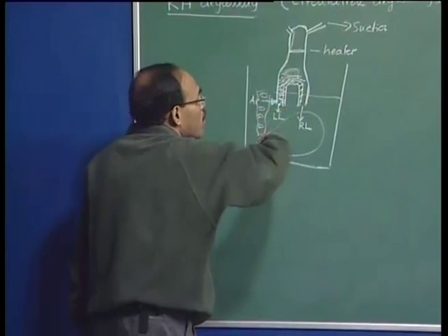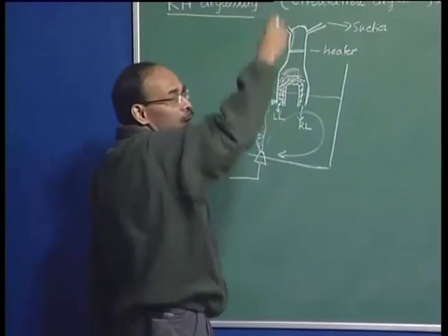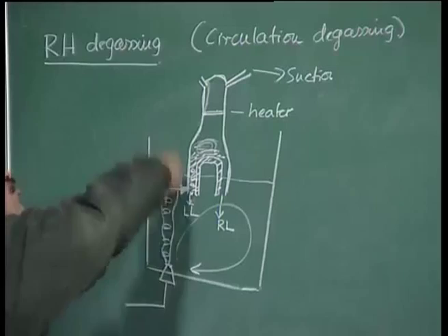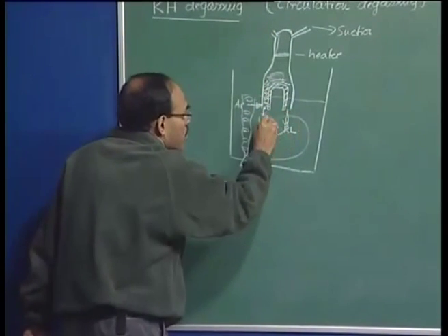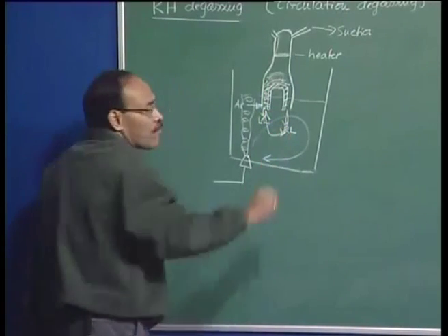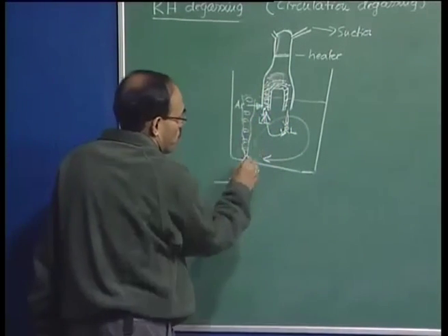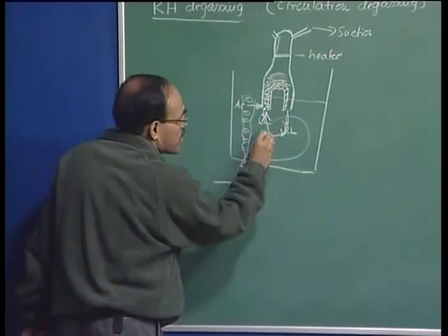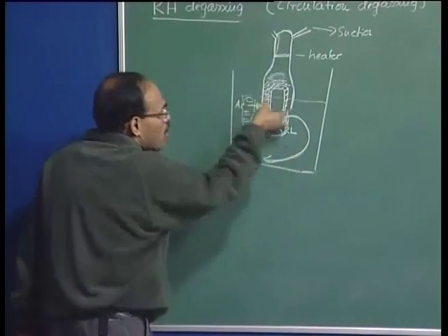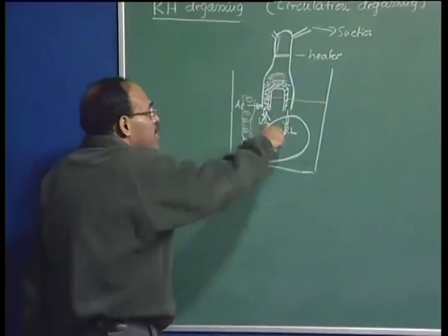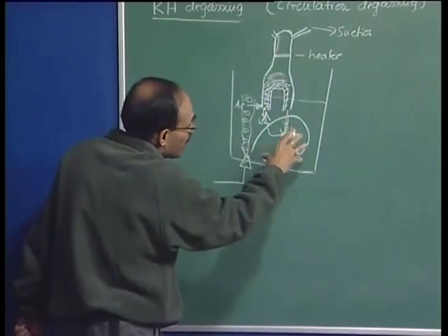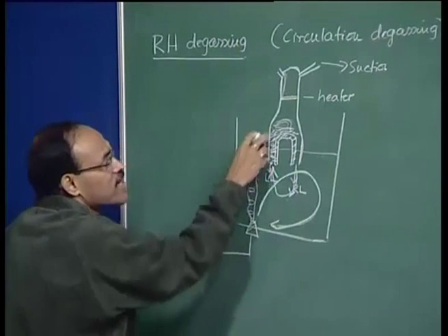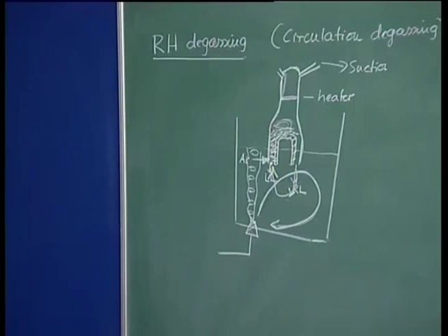So, there is going to be a lot of molten material drawn into the upward leg, and as the material is drawn into the upward leg, from somewhere the material has to come, and as a result some circulation is going to be set up. The argon gas injected through the porous plug is now going to bring more and more fresh material into the leg, and the circulation established here is going to expose all the material contained in this system to vacuum, and as a result the material will be effectively degassed.